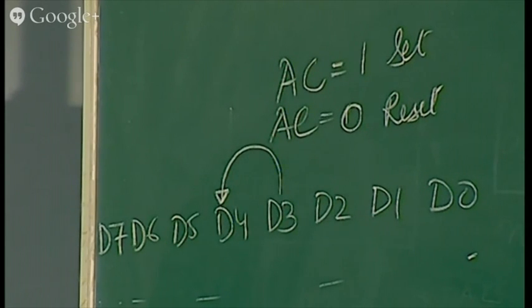When I'll tell you about jump instructions, तो jump में एक conditional jump होता है. जो conditional jump है, that is done only after checking the status of all these flag registers or PSW, program status word register, of the microcontroller. It's very important. Flag register is very important because normally कभी भी हमने decision लेना है, so decision will be taken after checking the status of this flag register.